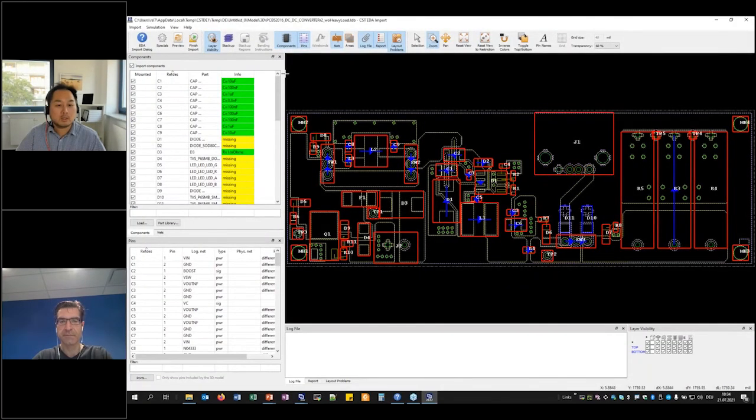And then here we go into the EDA import user interface, where all the components are recognized. For example, you can deactivate the whole import component, or you can activate it. Typically we deactivate this one because we'd like to replace all the components connected to the SMPS with the SPICE model.